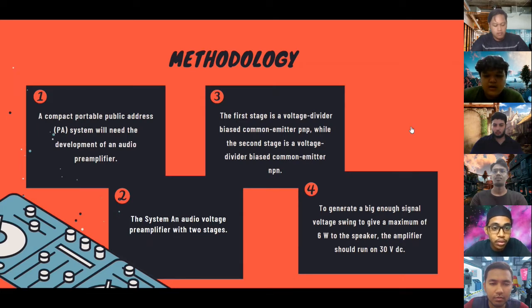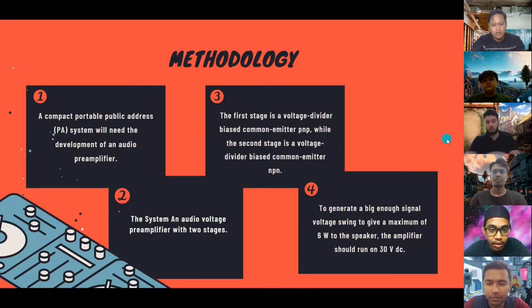The next one is for methodology for mathematical modeling. For a portable public address (PA) system will need the development of an audio preamplifier. The system is an audio voltage preamplifier with two stages. The first stage is voltage divider bias common emitter PNP, while the second stage is a voltage divider bias common emitter NPN. Then to generate a big enough signal voltage, we give a maximum of 6 watt to the speaker. Then the amplifier should run on 30 volt DC.